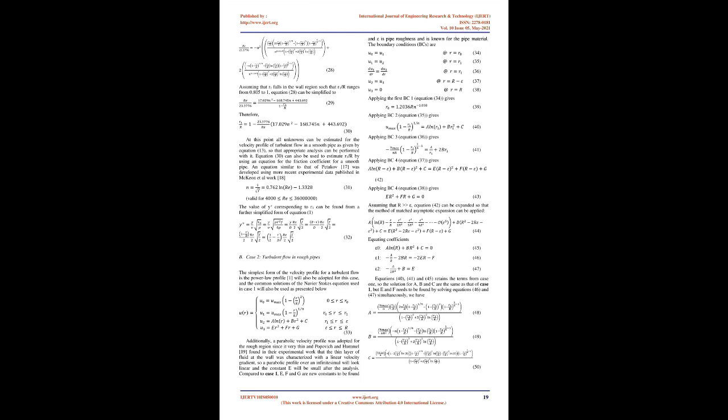Additionally, a simpler velocity profile which adequately describes the turbulent flow velocity in a pipe is the power law profile, given as follows. Experimental information on turbulence close to the wall. Experimental study of the viscous sublayer has included visual observation using ultramicroscope, hot wire.